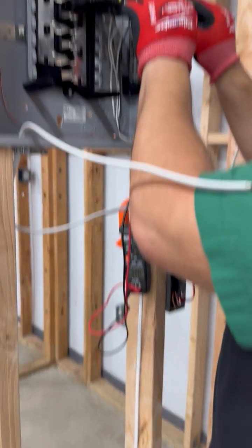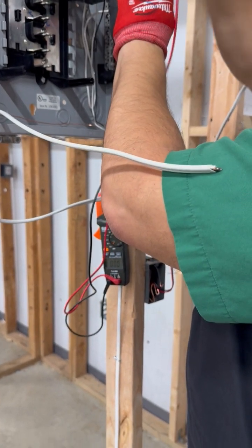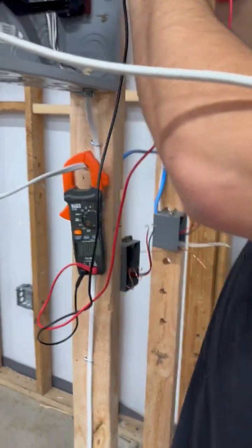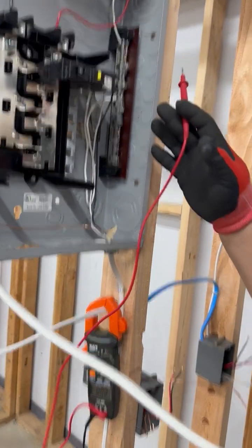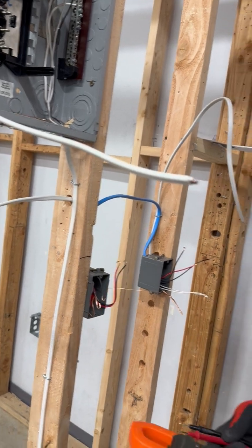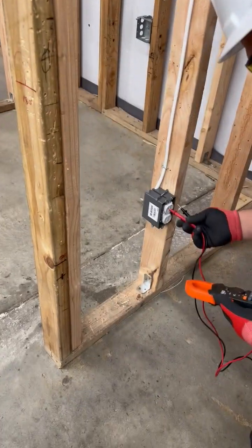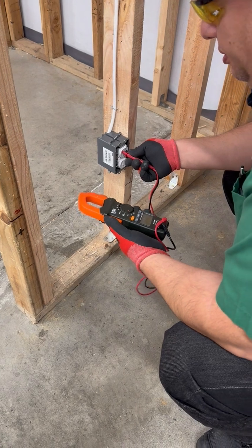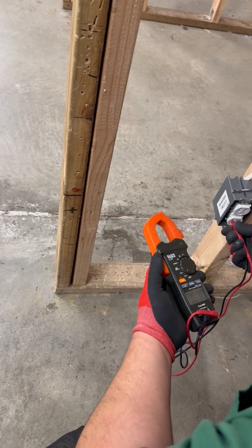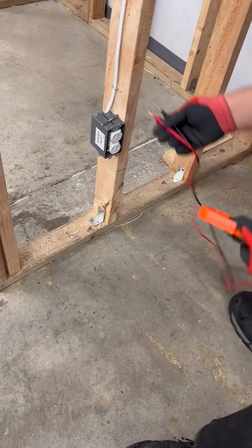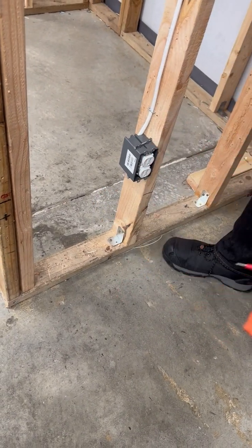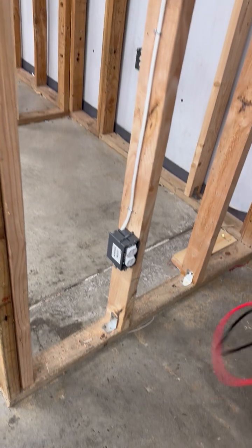I also want to make sure that once they energize their circuit, they check: do I have 120 coming out of the circuit breaker? Is it faulty? Is it correct? Once I know that is flowing, I'm going to bring this down over here, and make sure that they check the voltage at each of the ports. Do I have 120 there? Do I have 120 here? I don't want them getting the habit of going here on the side, because if they're using a metal box and they're not careful, they're playing that game of Operation, and then they ground fault and mess up the probes, they get an arc, all those things.